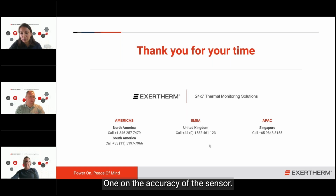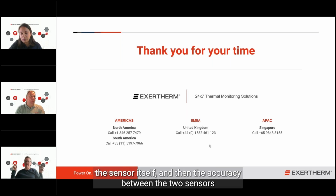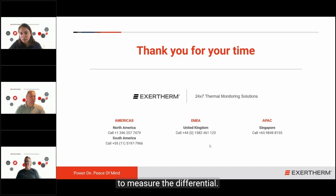One on the accuracy of the sensor. And it is exactly that. What is the accuracy of the sensor? And I'm reading into that question the sensor itself, and then the accuracy between the two sensors to measure the differential. Okay, the accuracy on an infrared device is stated as plus or minus 5%. Now, that sounds a lot.